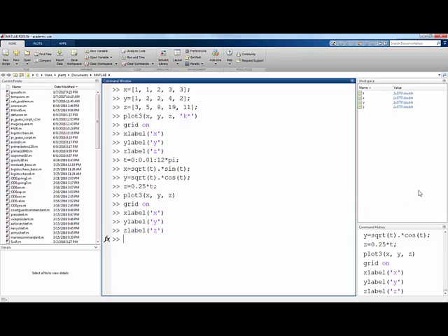In this case, the easiest thing to do, we need to get a 2-dimensional array of x and y values to define z over. And one easy way to do this is to use a command called meshgrid. So if you create a range for your x values, let's say -2 evaluated every 0.1 up to +2, and another 1-dimensional array representing your y values, I'll use the same range here.